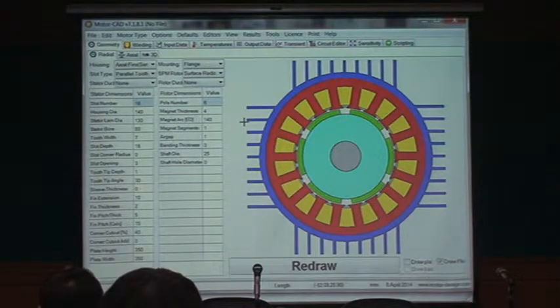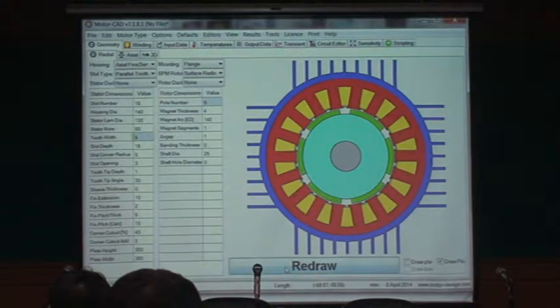And now we can see here I have all the information. We have the two threads, we have the slot opening and all of the things. As I change information on the go, let's say I'm going up to 9 millimeters in opening, you can see that the teeth were changed very quickly. Also, I have a little green marker that shows me what I have changed. So this is very cool stuff. I can actually track my changes as I go along.